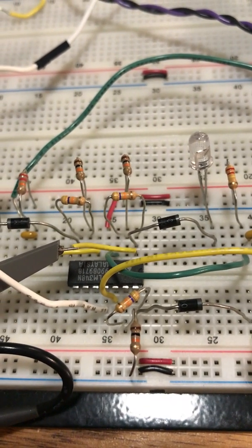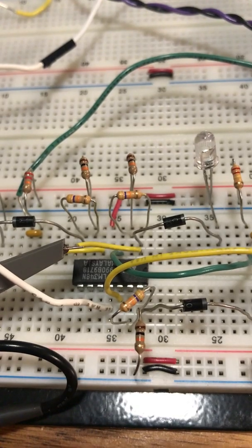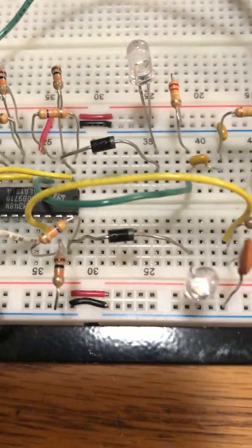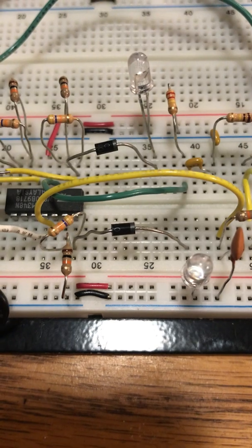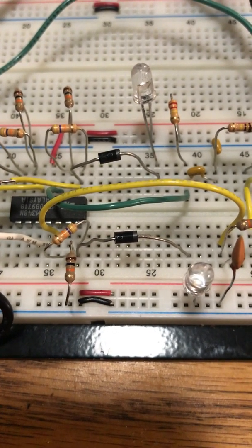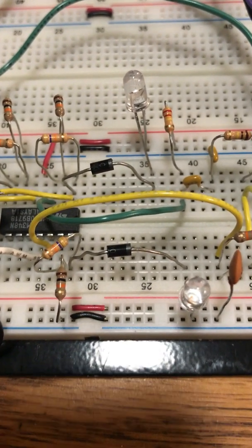Yeah, and then we pass them through a diode before the LED just to have a little voltage drop so the transition is smoother. It's not entirely necessary, because the LED is itself a diode, but we decided to keep them in because it works nicely.